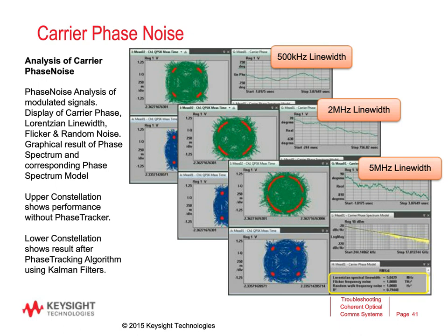signal on the lower constellation screen here to give you an idea how that signal could have looked without the phase noise addition. And also the optical modulation analyzer provides means to measure the Lorentzian laser line width, the flicker noise, and also the random walk noise. That's the yellow box I'm showing on the lower right-hand side here.